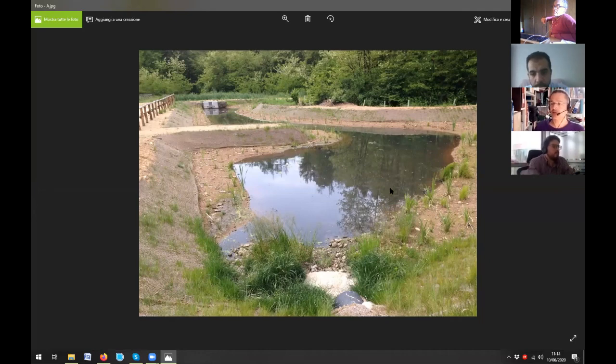Digging a hole is not that expensive, so this is a kind of last resort to get rid of the water. It's better to direct the water into this kind of quarry, which has been artificially created, so you can divert the water here, at least to cope with heavy rains. But first of all, you have to be sure that your drainage system exists, has been designed and realized.